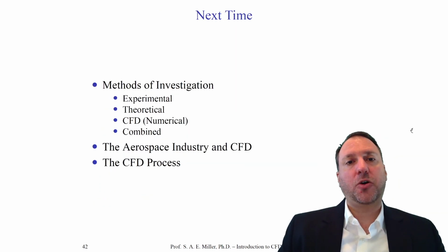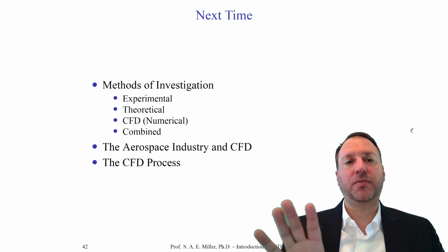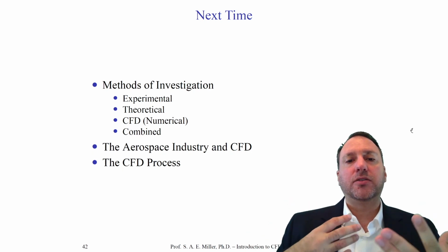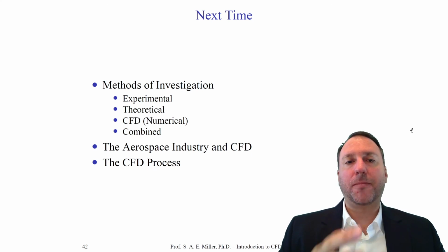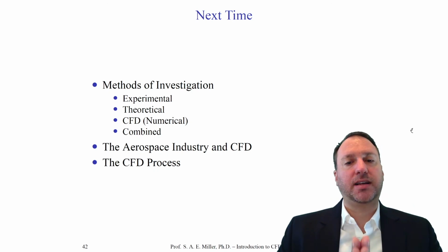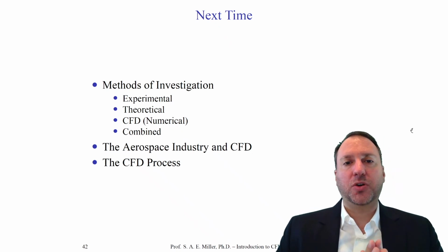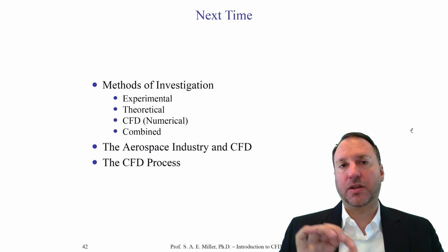Next time, we're going to go back to the beginning and look more in depth at the overall field of CFD. During this time, make sure that you have your solver running, your visualization software running, and your grid generation software running. Try this initial tutorial multiple times to get used to it and ingrain it in your mind. These are the most basic concepts of operating a CFD code, which is research-based, industrial-based, that there is. Now, commercial codes with fancy and beautiful graphical user interfaces are doing some of these steps for you automatically. But by learning to do them, you're finding out and learning the fundamentals.